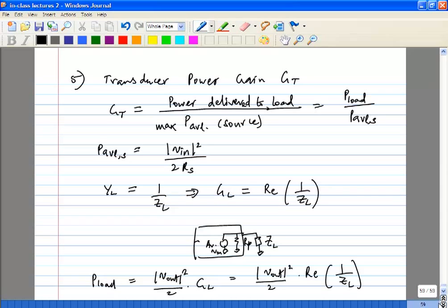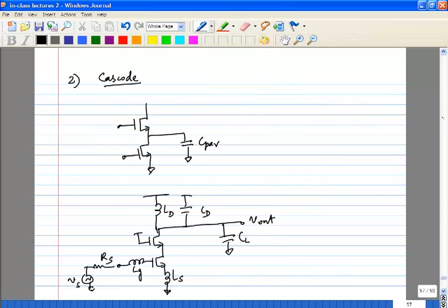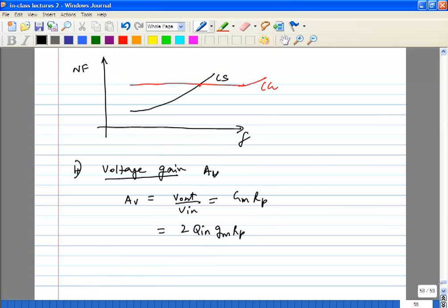So why did you put RP in parallel? RP is actually in parallel, if you look at the common source, right? So the RP is the resistance of the tank and output impedance, it's actually in parallel. AV actually included RP, remember that? AV is actually GM times RP.